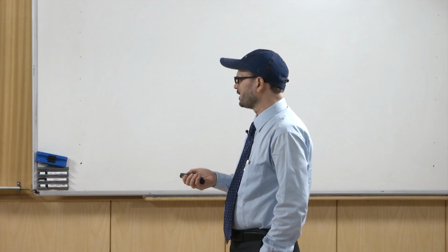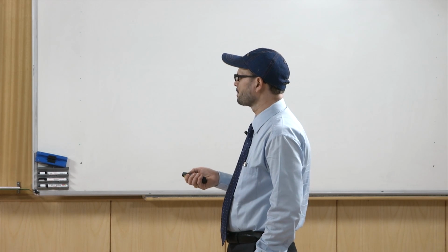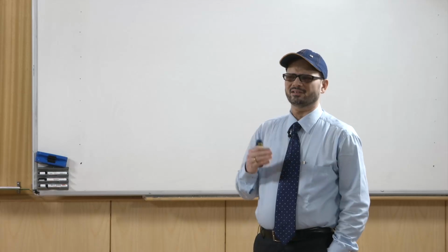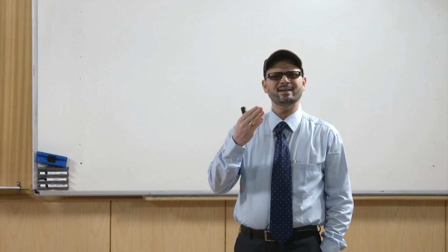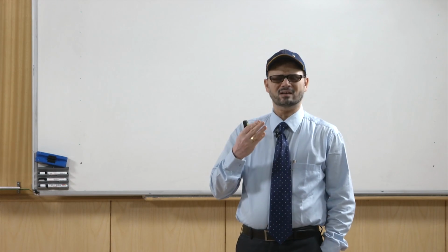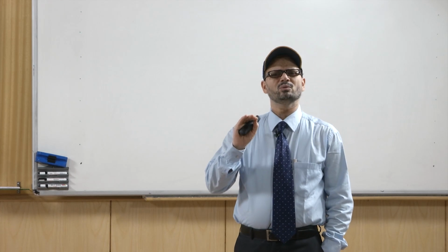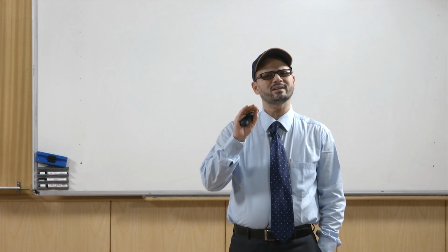So, that is why in the casting, suppose this is a mold cavity, a riser is placed in such a manner that it should be able to supply the molten metal in case of shrinkage. So, the main purpose of the riser is to supply that liquid metal when it is required. It is also known as head or sometimes feeder, because it serves the purpose of feeding the molten metal which is required by the casting during its solidification.